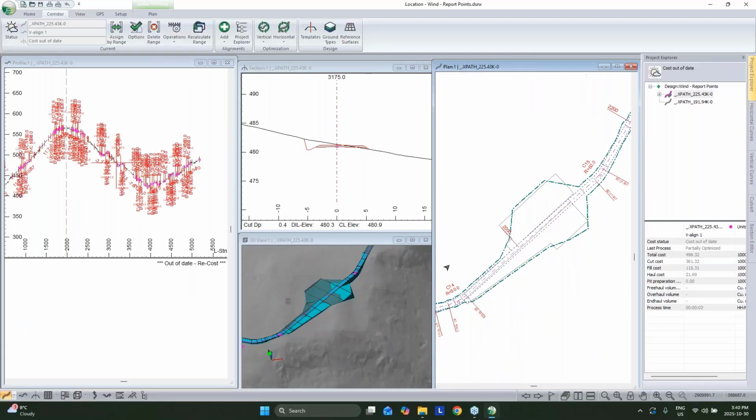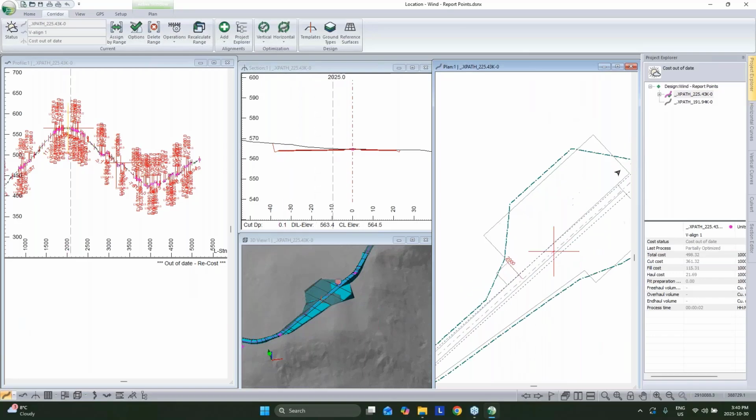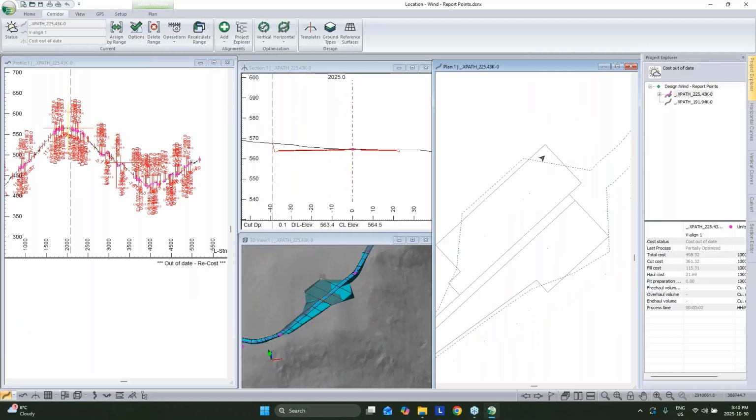In this particular example, it being a wind farm example, I have my pad geometry defined based off the extents of a reference feature. That reference feature is this line visible here in the plan view, but I'm not catching the edges of it perfectly. Now we're dealing with a cross-section model, and if we want to get a better representation of where we should start transitioning back towards the road edge from the pad edge, report points will be helpful for that.